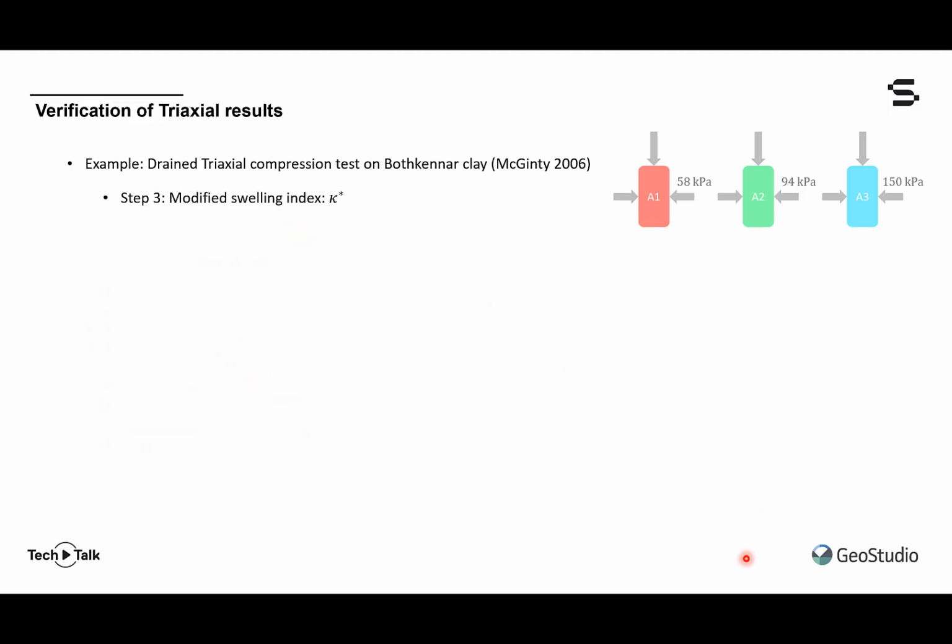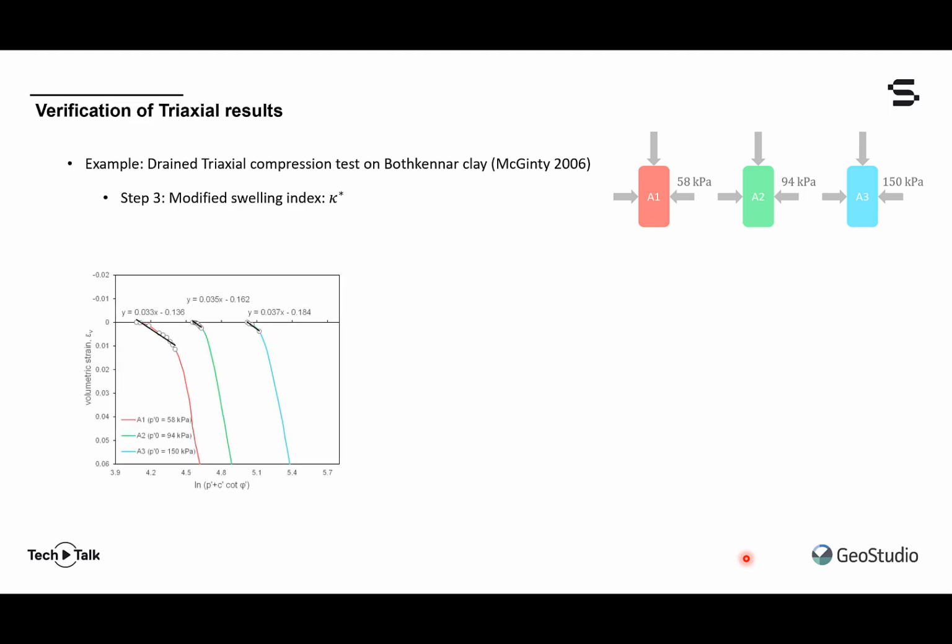The third calibration step can also be applied to the triaxial test data mentioned previously, that is, the overconsolidation branch in each of the three curves, except now we're looking at our volumetric and confining stress plane. You can see here that the entire path is presented, but we've isolated just the elastic data in all three cases.